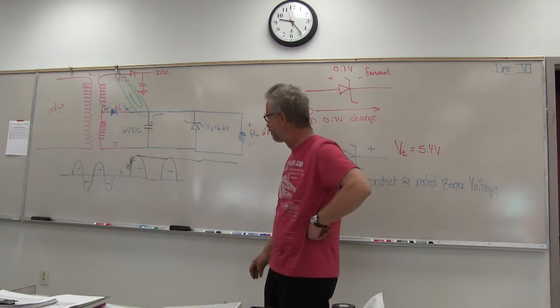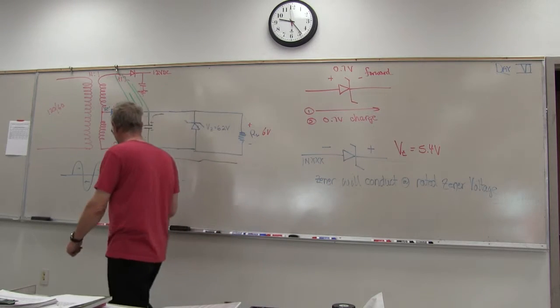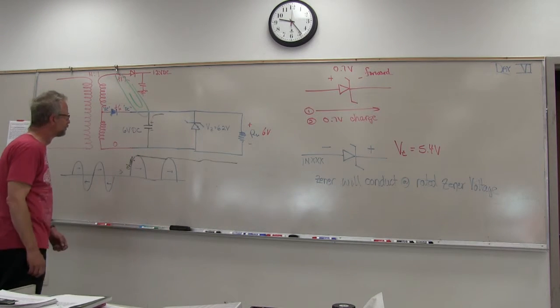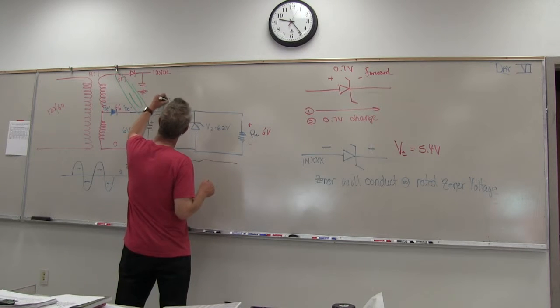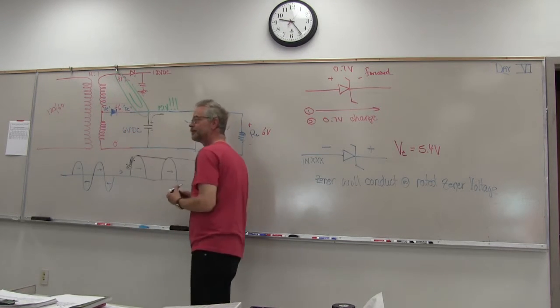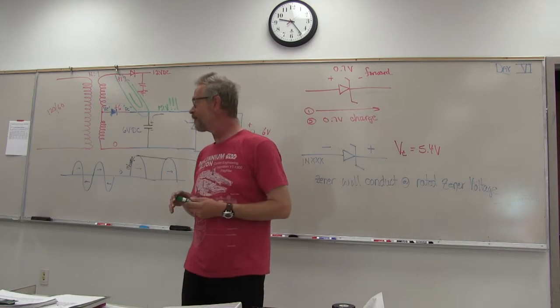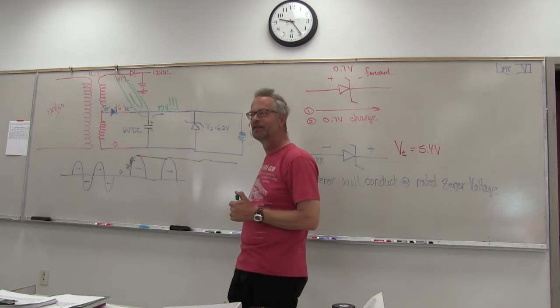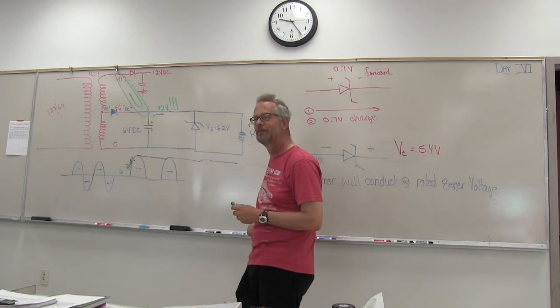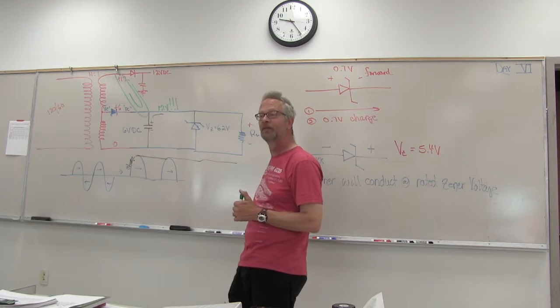Nope. This is going to want to go where? Up to 12 volts? Because we have a paper clip that connected our 6 volt line to the 12 volt line. Not a good plan, right? You see how that happened?